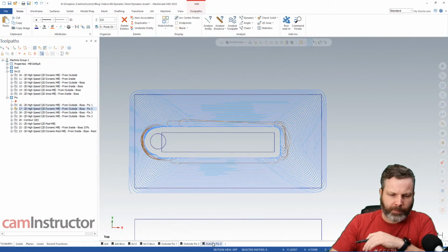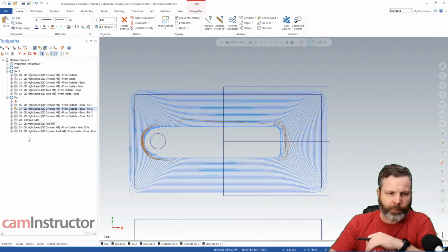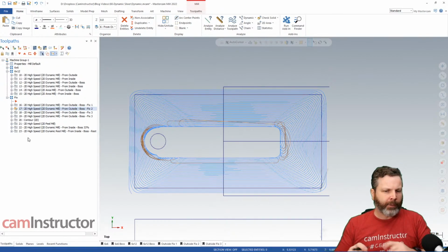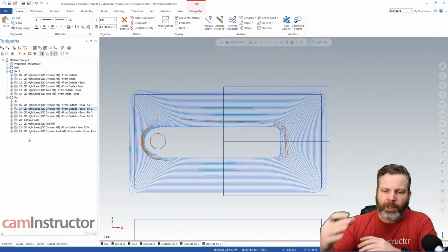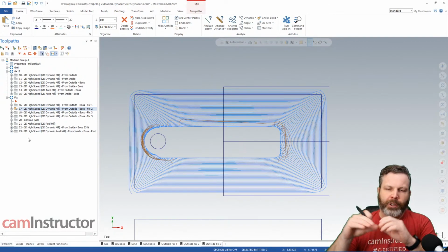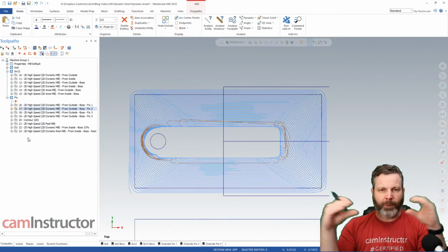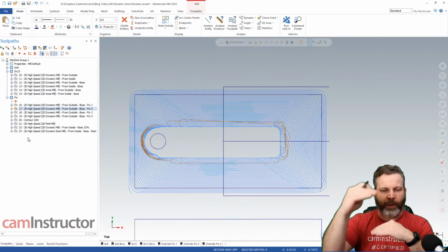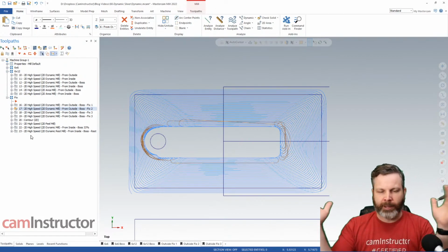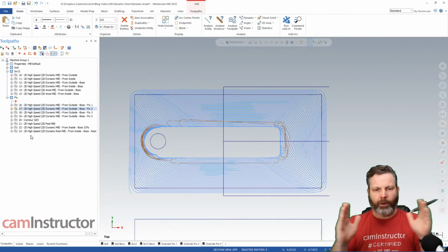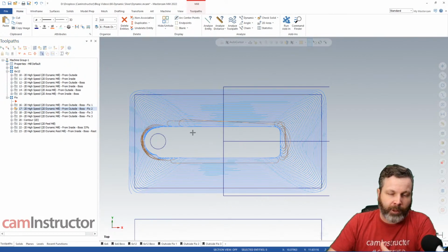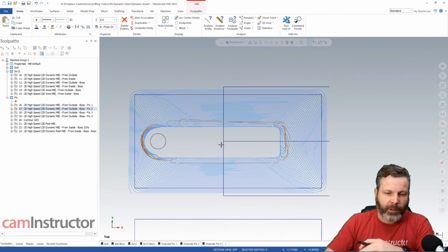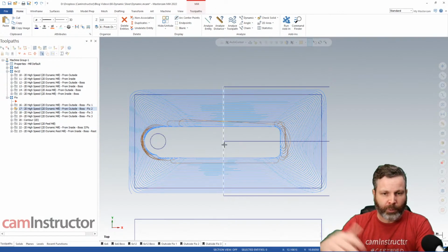Other options, let me go for maybe the most obvious one, but before we get into more of these, another way you can look at fixing this toolpath is you just need to eliminate the disproportion between the width and the height. If you can get that squished down to being more of a square-ish shape, the closer you get to square, the less sliver there'll be here, and the less you need to worry about it altogether.